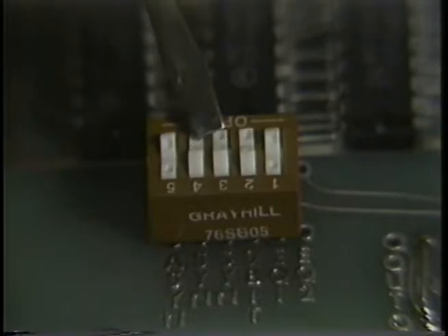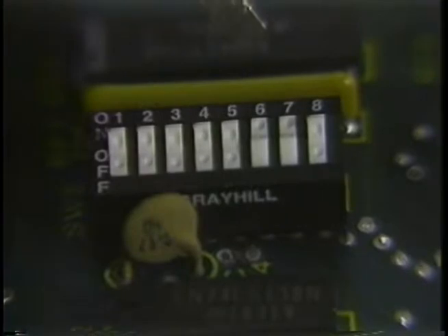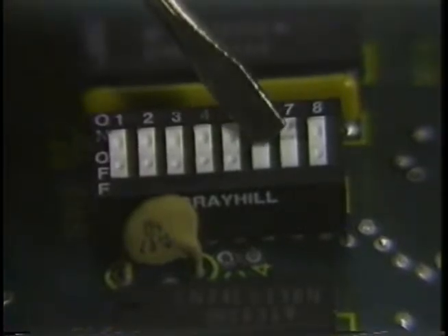While 212 type modems can be used for synchronous communications, a good guess is that 90% or more of 212 modems are used asynchronously. 212 modems can be optioned for asynchronous word lengths of 9, 10, and on some, 11 bits. The typical word length is 10 bits. The 10 bits include 1 start bit, 7 data bits, 1 parity bit, and 1 stop bit, for a total of 10. There are almost no 9-bit applications. The 11-bit word length is usually limited to Wang and Nixdorf computers.